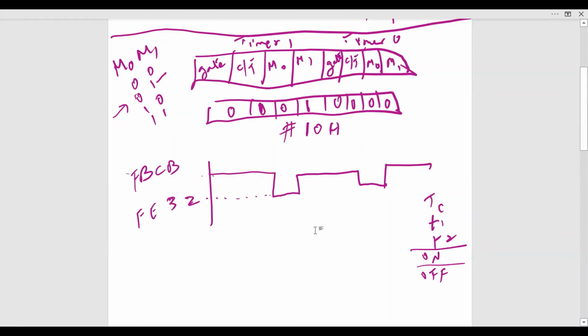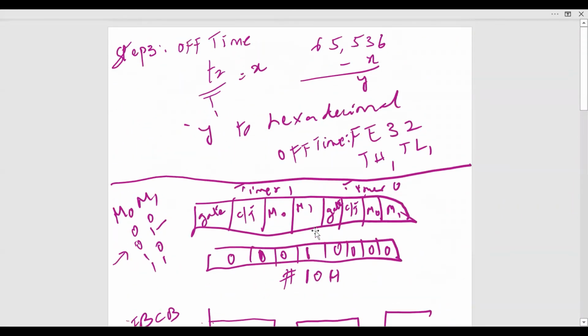I hope you all understood, and also I hope you understood what this value is, because the counter is a 16-bit timer. It starts from 0000 to FFFF, the maximum number. And if you want to get back to 0000, you have to add 1 to it. So I have converted this into a decimal number. The equivalent of FFFF is 65,535, plus 1, that is 65,536.